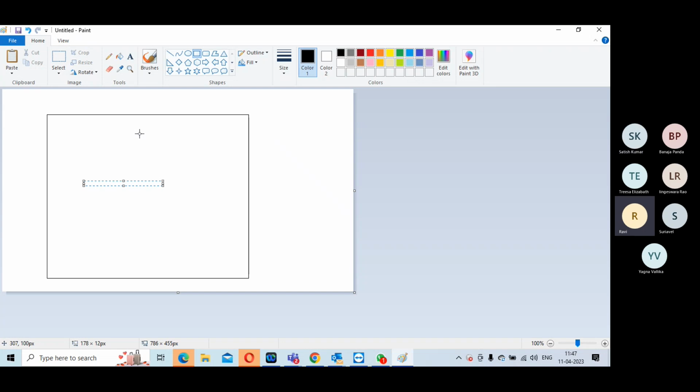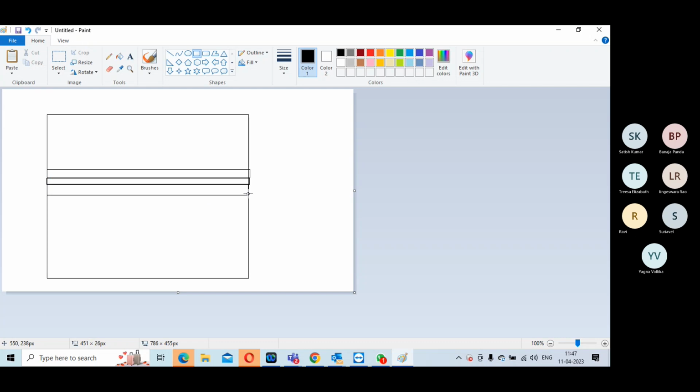Because the way you place tap cells is important, 50 micron is not just standard. I will tell you how. Let's take this as your first circuit row. Just for illustration purposes, I am drawing three circuit rows. These are your three circuit rows.